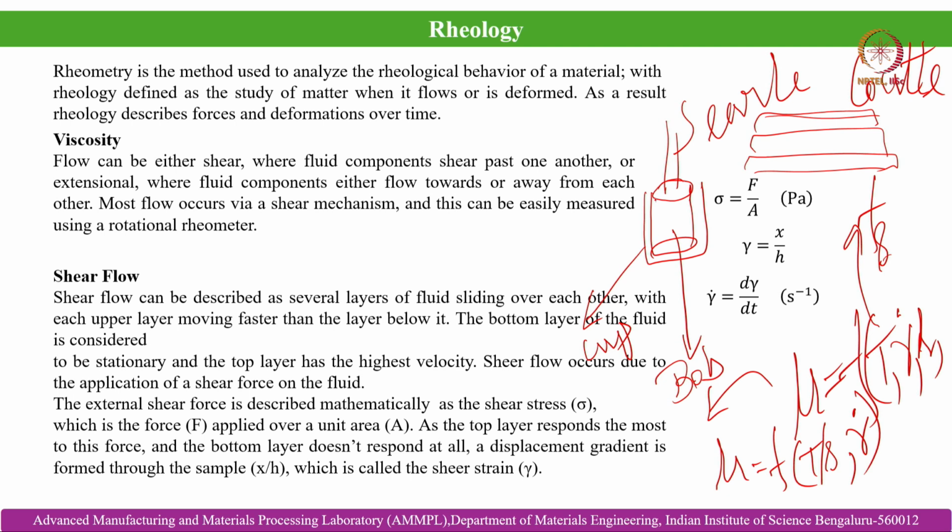In the case in which the cup is stationary, the bob, which of course has to be a grooved one, facilitates shear within the liquid melt, which may be kept isothermally at a particular solid fraction in the semi-solid regime or in the completely superheated molten liquid state. This is the case of a Searle type rheometer. Then there can be a Couette type rheometer as well.